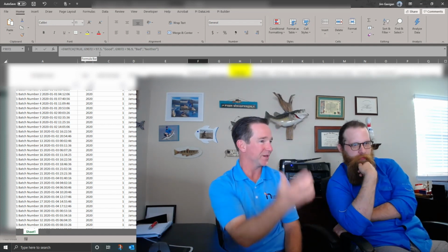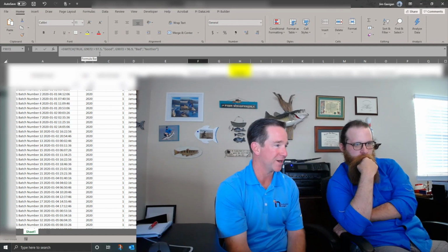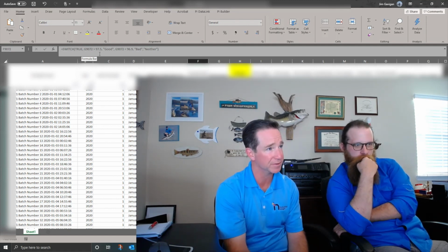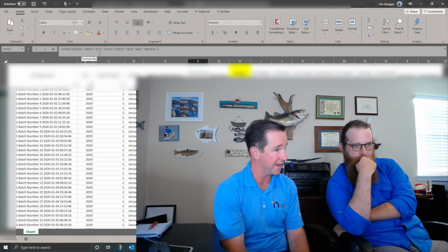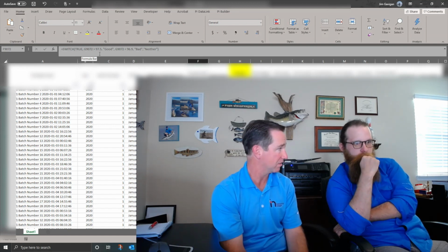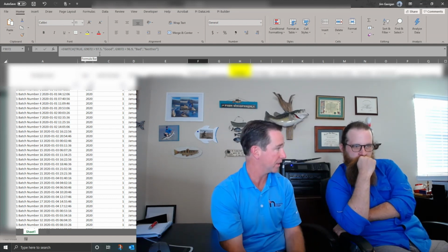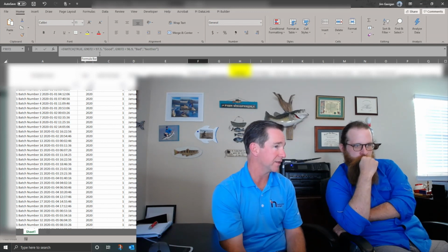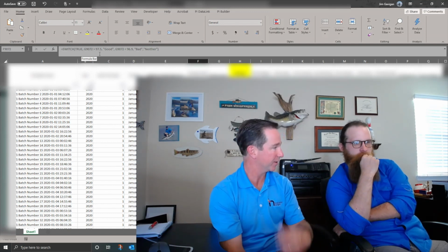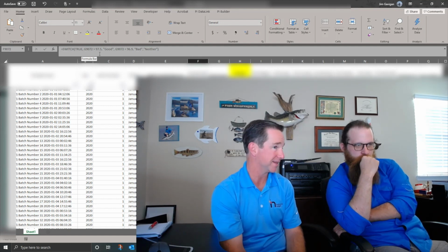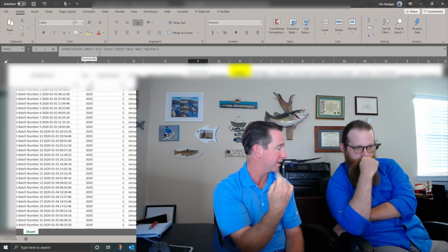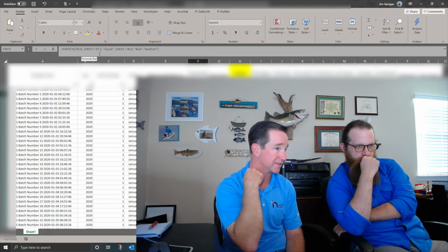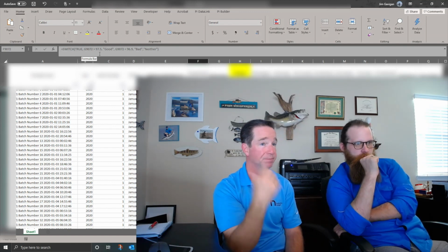A real data scientist might have done that, but I just eyeballed it. So I said, let's look at 96.9 and below is bad, 97.5 and above is good. And if it's neither, I'm just going to mark it neither. Then I can use that as my class ID for my discriminant analysis, and I can choose to ignore the neithers as I'm importing it into SIMCA. So it'll have three classes, good, bad, and neither, but I'm choosing to ignore the neither class. It will eliminate all those rows that say neither as I bring it in.